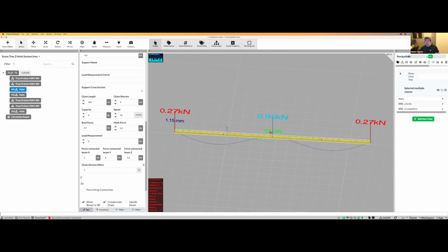The main problem is that this calculation effect you're seeing has nothing to do with Production Assist or FEA calculation in general. It's just a property of any calculation like this. The reason is that the actual forces on the truss depend on the masses beforehand, because you need to adopt specific assumptions in order to do this. So every time you get a structural calculation from an engineer, or do one yourself, you're making these assumptions. And if you don't match these assumptions, you will not reproduce your structural calculation.